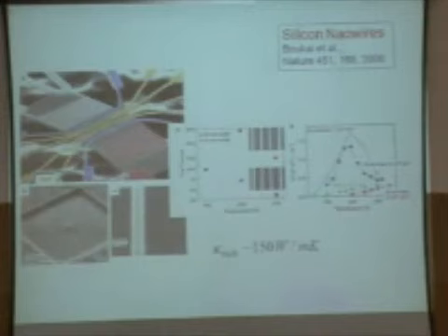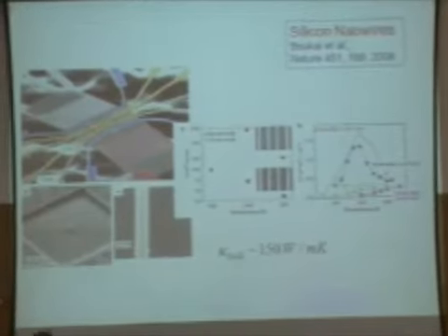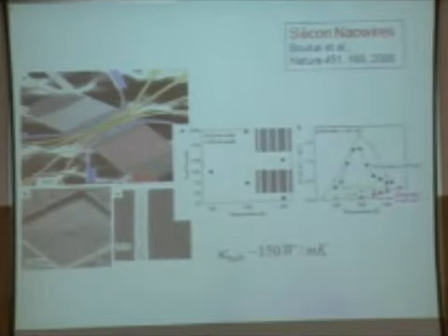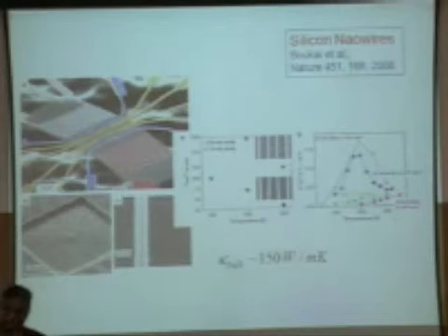You can see the world is quite hard. Whether it's an efficient way of using energy, we don't know, because the amount of money and energy you spend to build this is perhaps much, much larger than the power output. But what they found was a very interesting result. When you made these nanowires of silicon, bulk silicon's thermal conductivity is over 150 watts per meter-kelvin. Here I'm plotting bulk by nanowire, and the reduction is dramatic, about factors of 100, 200. Translated to simple language, when I make nanowires, the phonon heat conductivity reduces dramatically by 2 orders of magnitude. And that, I think, is a big gain in this whole field.